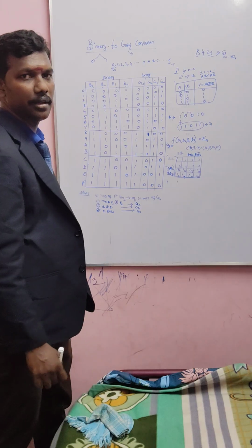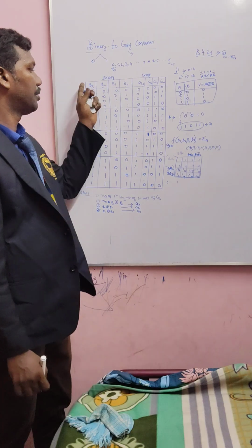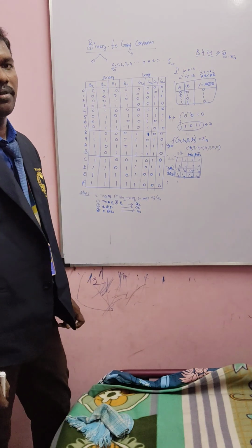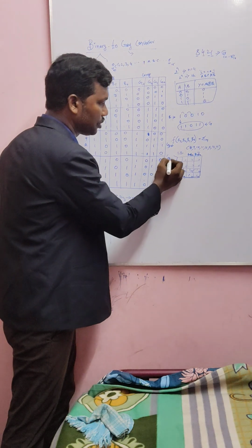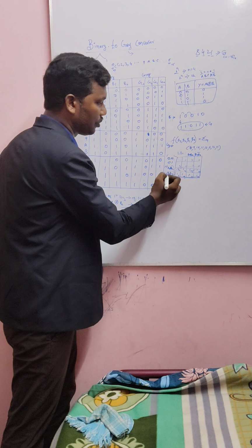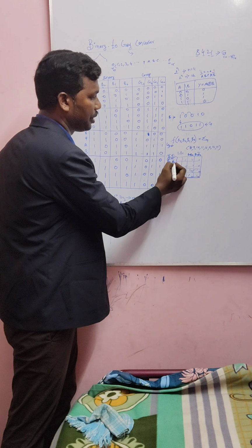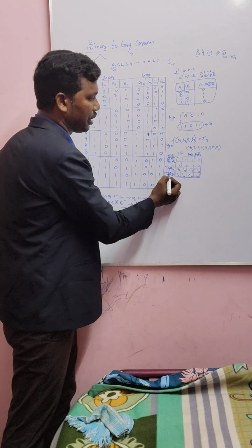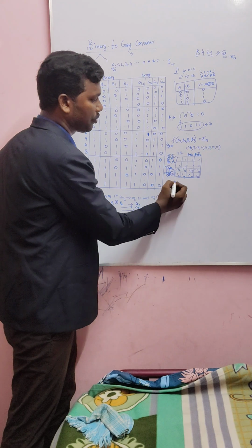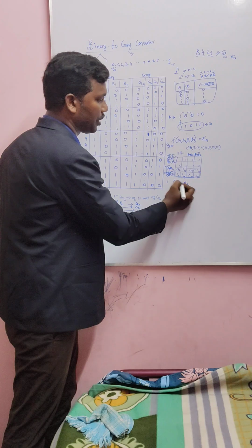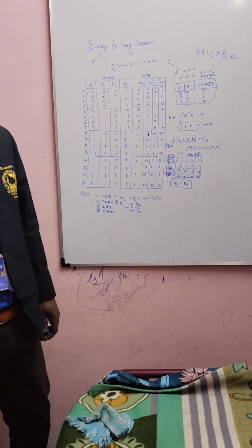And here the combined case, what it actually is, right? So you just take it, that particular number will come to these cases, right? So what we are trying to say is, here this case will be 0 0 0 1 1 1 1 0. So B3 bar B2 bar, B3 bar B2, B3 B2, and this is B3 B2 bar. So here the common term is B3. Okay, common term is B3. So G3 is equal to B3. What we actually did in the truth table, the same will come to us, right?